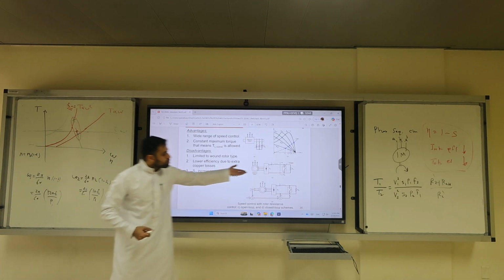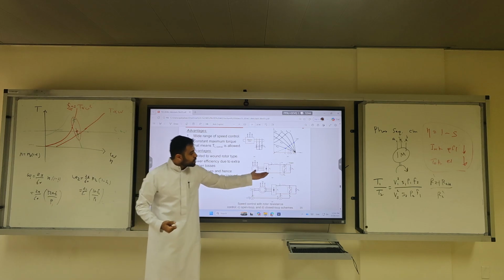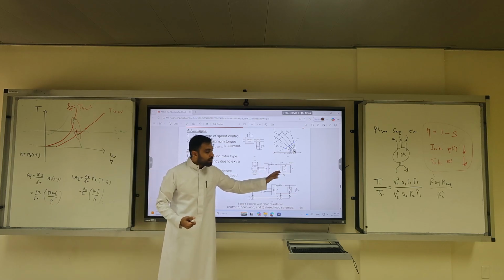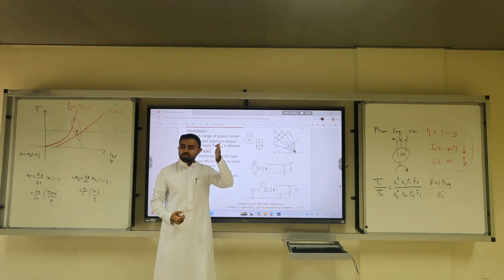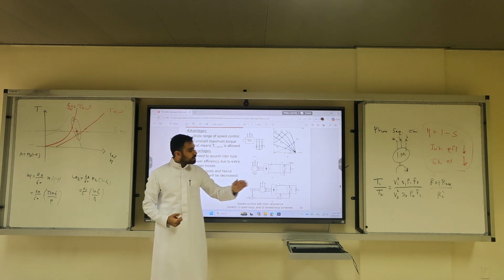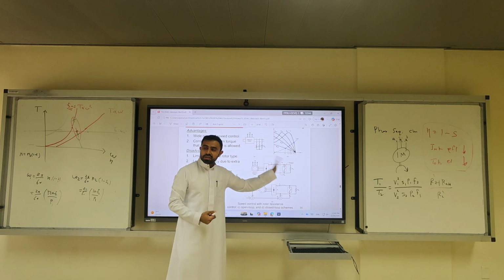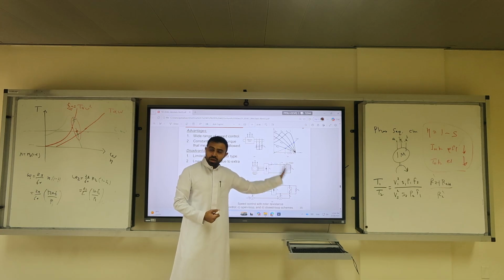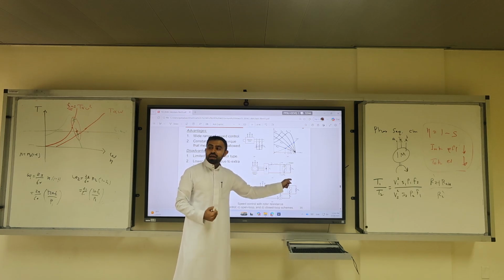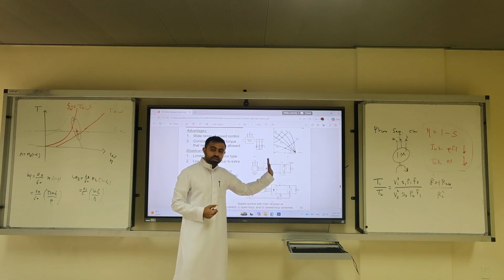Here is some power electronics technique. This is what we call a chopper. Instead of having RX1, RX2, RX3, you have one big resistor and you switch this using power electronics to get an average RMS. If you keep that breaker open more, you expose the external resistance on the RMS more. If you close it more, you make it more short circuit.